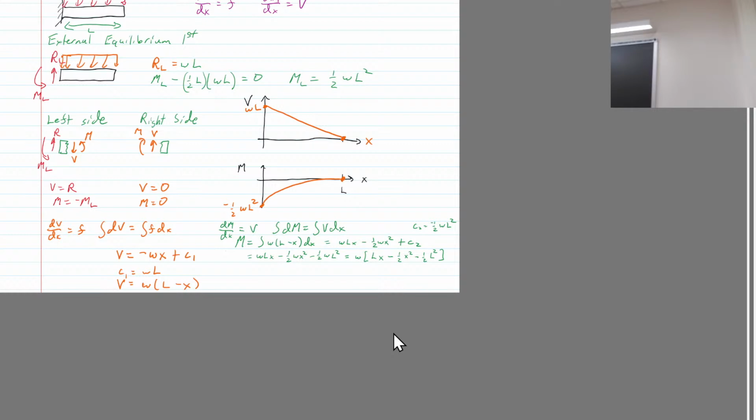So no bending stress. There is a bending moment, you're right. There's an internal bending moment, and that's going to be given by PY times A. But the bending stress is 0. So then it's going to be tau V minus tau T, at least for that stress.